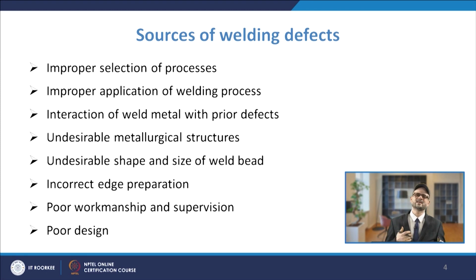There may be many reasons: you may have overfill, you may have overlap, you may have undercut. Basically, for having the ideal properties, you want an idealized shape of the weld bead.